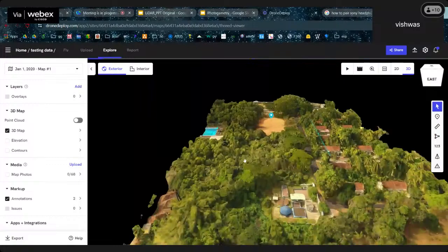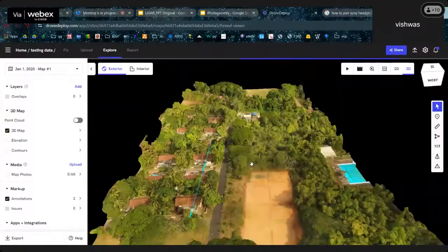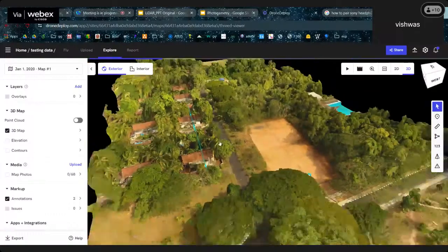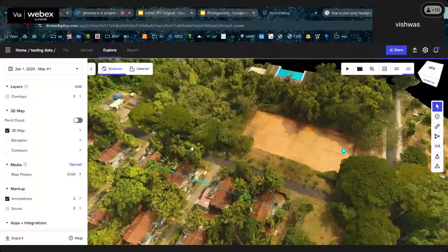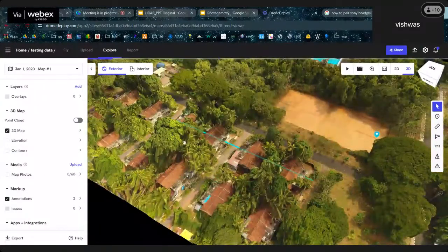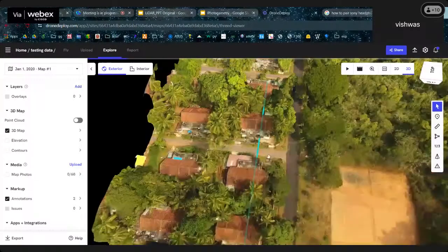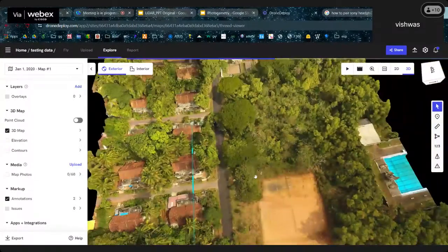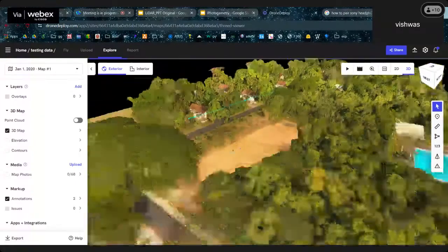So this is a 3D model. It will take some time to load. Based on the survey, to get proper 3D data, we need to take each image from about 5 angles, one from the top and one from each side, at least four sides. Then only will we get proper 3D data along with the side walls and all. Right now, only nadir images are processed, but still we are able to get where the trees are, how high they are, all the details about this.